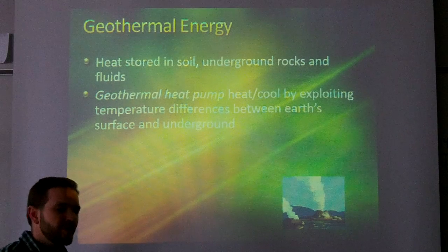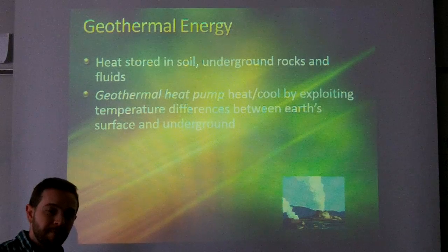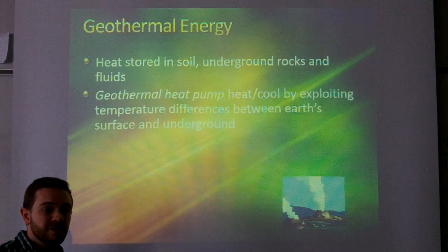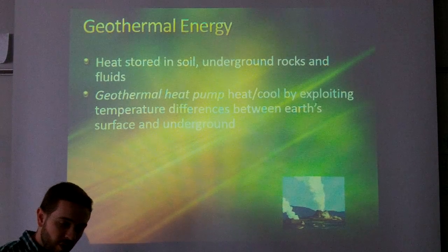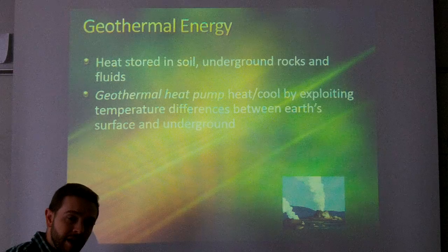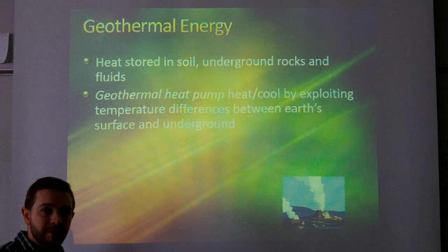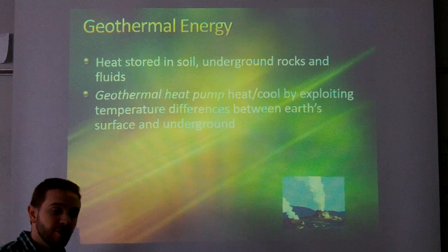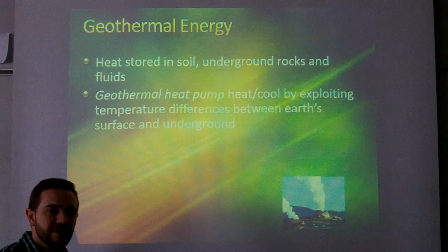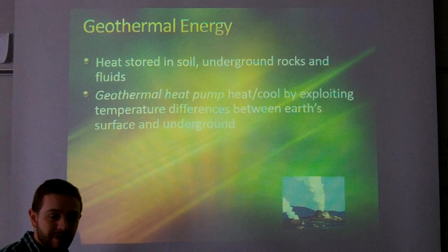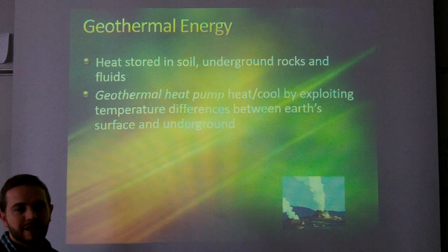In geothermal pumps, you only have to go down 10 to 20 feet into the ground to get enough of a temperature discrepancy to then pump down fluid. Some just use water, right? You can pump water down there in the summertime, and it will cool off underground and then be used to cool your house. In the wintertime, it's warmer than the ambient air temperature, so you can pump it there. And even if it doesn't heat it up all the way, it at least preheats some of the water or some of the air that's being pumped down there. Then you have to use less energy in a furnace to heat it the rest of the way so it's comfortable, okay?